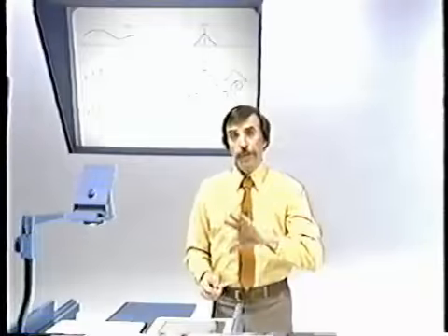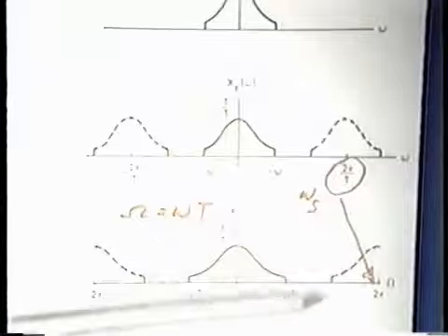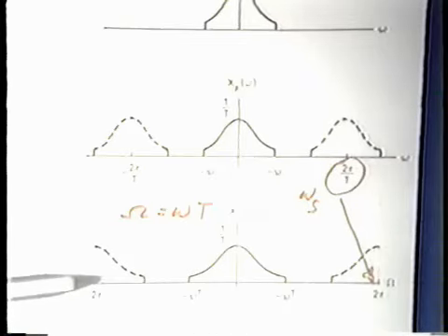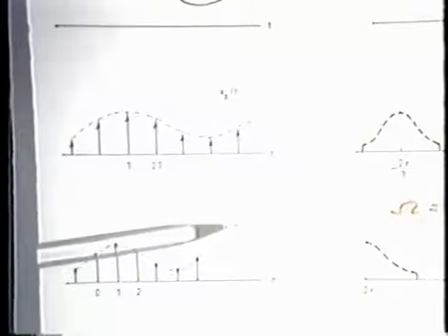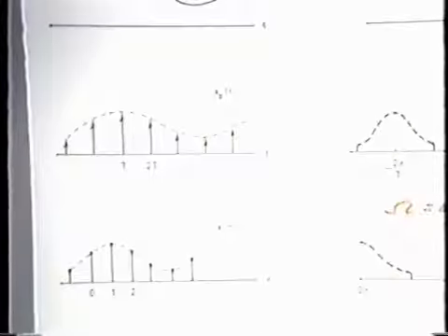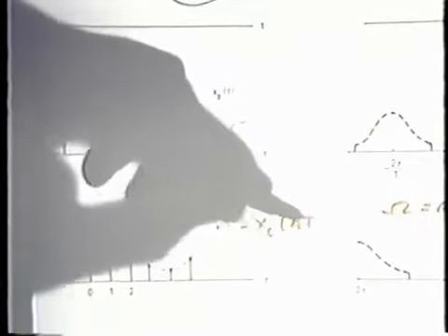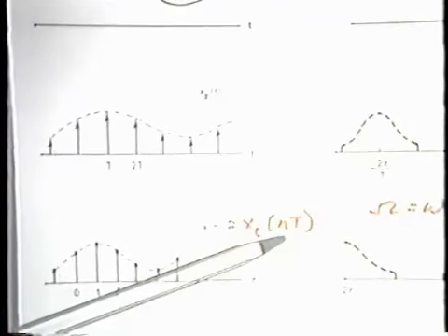And so in the frequency domain, there is a frequency normalization associated with the fact that corresponding to this spectrum is a discrete time sequence, as I showed previously, and the discrete time sequence is related to the original continuous time signal through a time normalization. In other words, these sequence values are simply samples of the continuous time signal with the time axis renormalized.